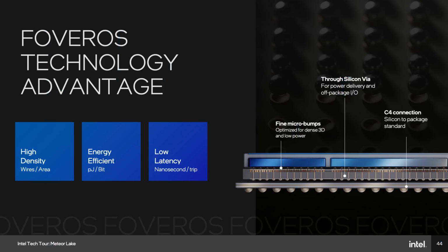The concept of having multiple dies within a single package isn't new, but Meteor Lake is revolutionary with the notion that we're going with a Foveros 3D construction. So what happens is that we have all these tiles or dielets on the top, and there's a base die sitting below, which is where you have the connection. Let's say compute wants to talk to the SoC: compute will go down through this base die, come up, and talk to the SoC.